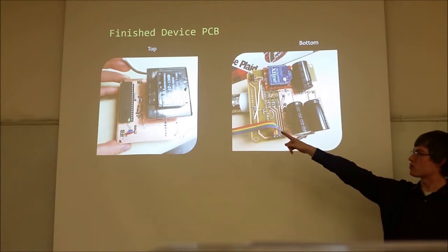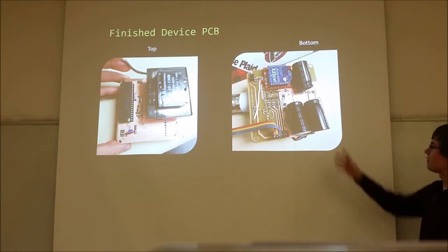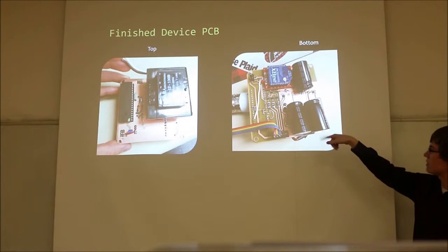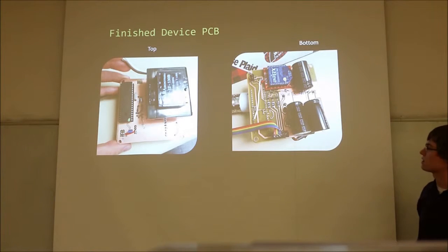And this is the top side of the PCB here with, as you can see, the PIC, the crystal over there, 20 megahertz, and the transformer. And on the bottom side here, the one facing the light itself and the floor are the 3 bank capacitors, the Zigbee, as well as the FET control circuitry for the LEDs.